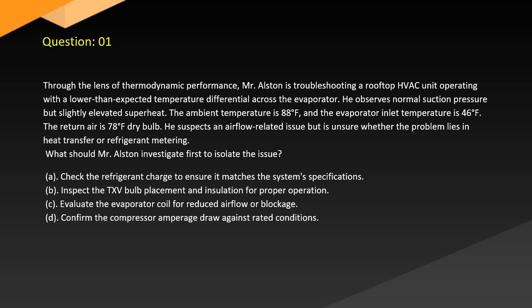A. Check the refrigerant charge to ensure it matches the system's specifications. B. Inspect the TXV bulb placement and insulation for proper operation. C. Evaluate the evaporator coil for reduced airflow or blockage. D. Confirm the compressor amperage draw against rated conditions.